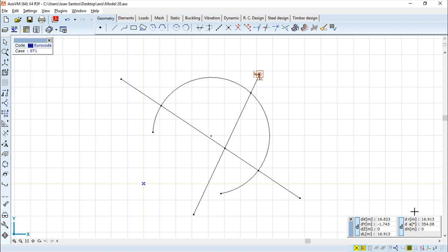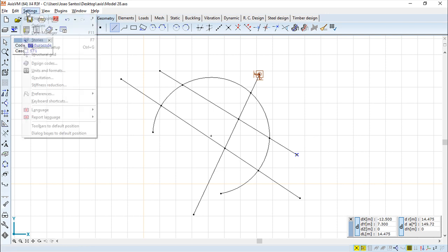Finally, we have something called auto intersect. If you look at the geometry we've created, and I will create a new one, when I create, for example, a line, you see that on the intersections it automatically creates nodes, and the entities are automatically broken down into simple entities. This is a functionality called auto intersection. This is the standard behavior, but we can also change it.